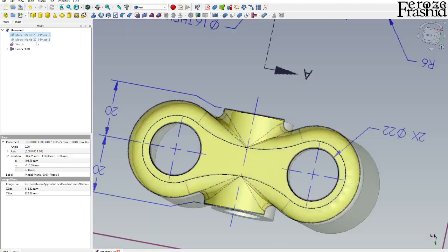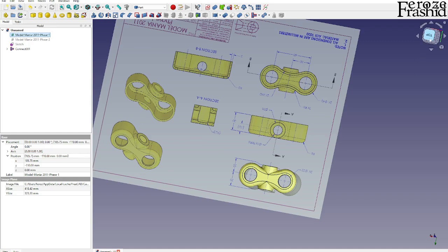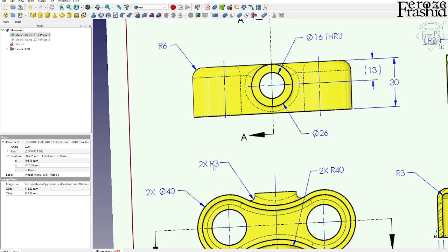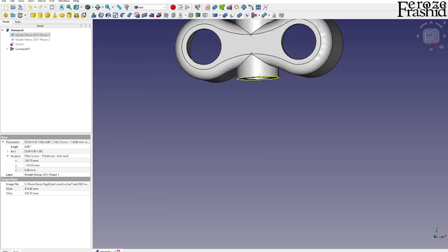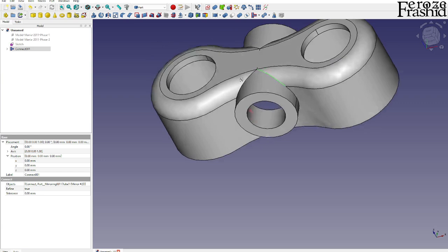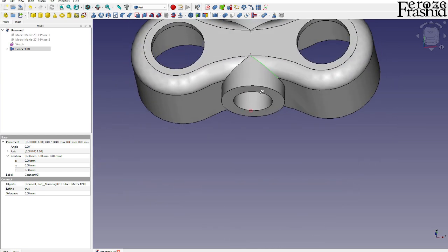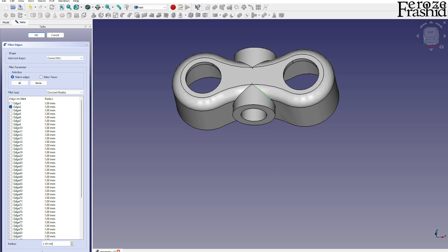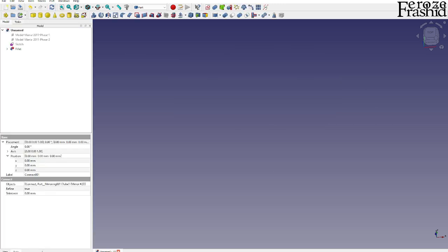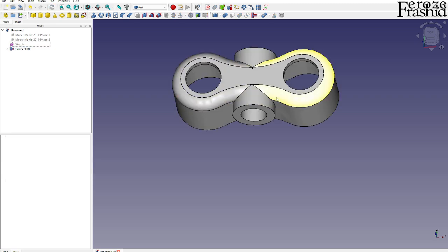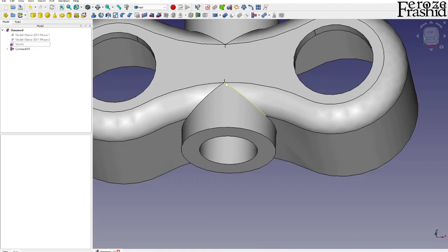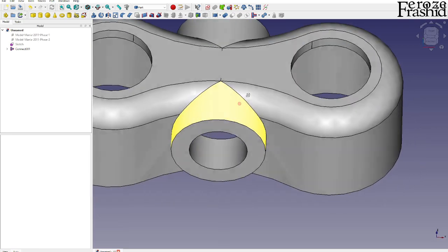Okay, so I think that's the end of the phase one, except that we didn't do the filleting thing. This fillet is radius 3, so this edge will have to be filleted for radius 3. Let's see if it works. So we want to say this is 3. It did not. Okay, because here it's matching, it's too many connections at the same point. So we'll have to do something about it.